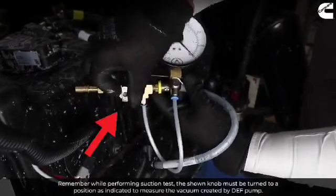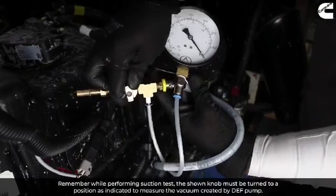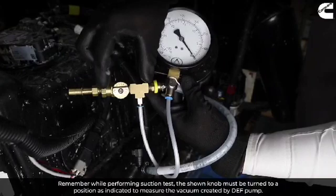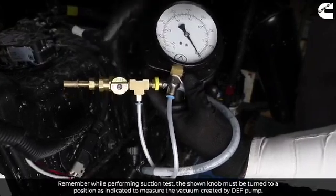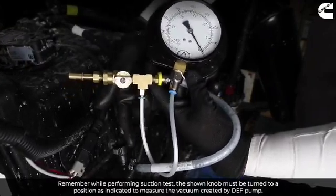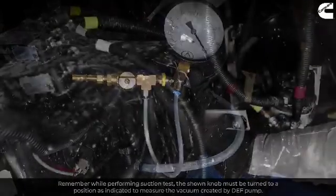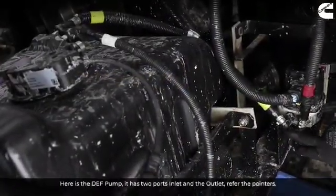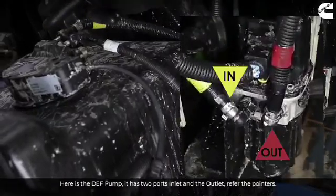Remember, while performing the suction test, the shown knob must be turned to a position, as indicated, to measure the vacuum created by the DEF pump. Here is the DEF pump, it has two ports, inlet and outlet, refer to the pointers.